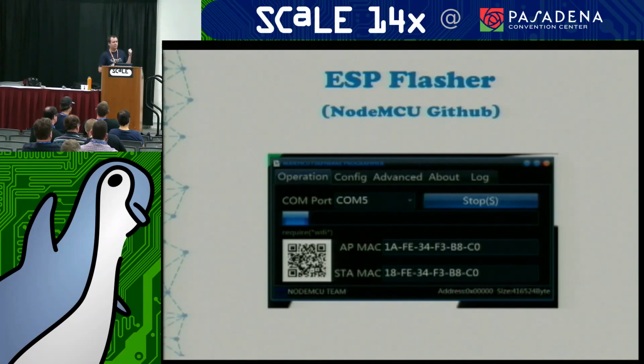So software side, how do these things work? You can run the Arduino IDE with these ESP8266s, but you can also flash it to something else, anything you want. You could build your own firmware and your own development and your own code and language to use with it. By default, it comes with the Lua programming language, so it's got a firmware that includes the IP smarts and the web interface, and Lua is the language you use to program it.